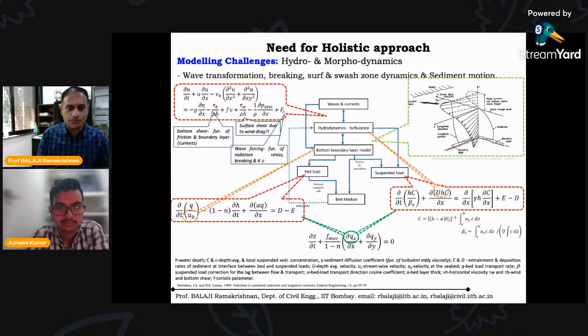I think all of you would have done an experiment called the Reynolds dye test as part of your fluid mechanics lab, where we have a vertical tank with a pipe, and a valve, and you have a red or blue color dye being injected at the middle of the pipe, and the opening of the valve will make a laminar flow transition to transitional flow and then to turbulent flow and so on. If you look at the dye streamlines or streak lines, the dye will be very uniform during the laminar flow. And then the more the valve opening, the more it leads to a turbulent regime. You will never be able to recreate the same scenario even in your own laboratory, however accurate the opening of the valve. Okay, so this is one simple example of how turbulence cannot really be understood properly.